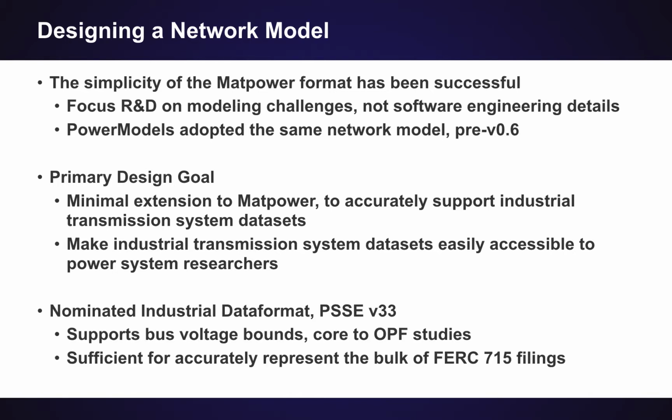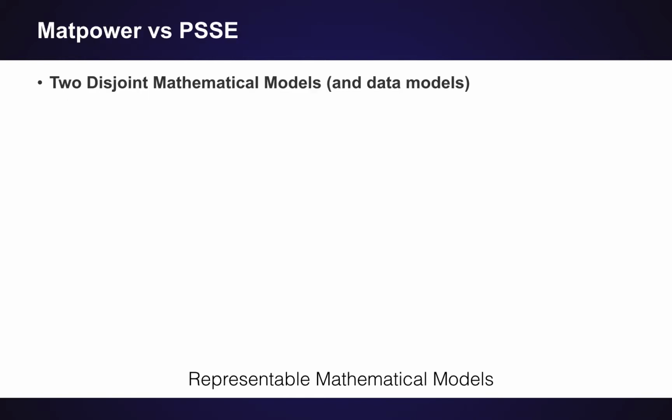We have nominated PSSE version 33 as our standard industrial data format. Why have we used this one? The first reason is that it supports bus voltage bounds, which are a core part of AC/OPF studies, so we would very much like to have those in the data format. And then our second reason is that we observe that it's sufficiently accurate to represent the bulk of FERC 715 filings, which we presume is a fairly accurate model of what a transmission system dataset for system planning is.